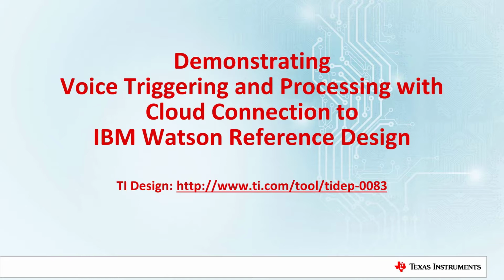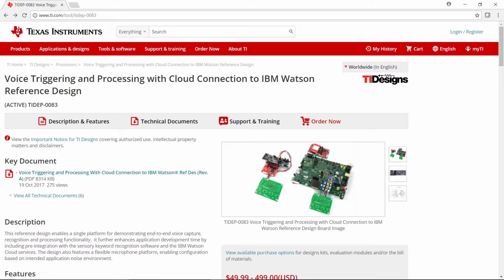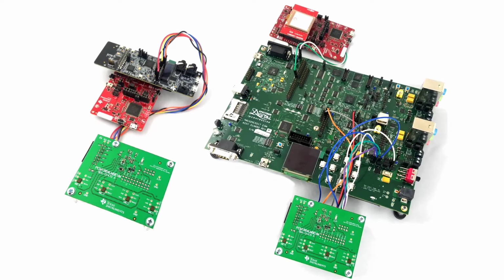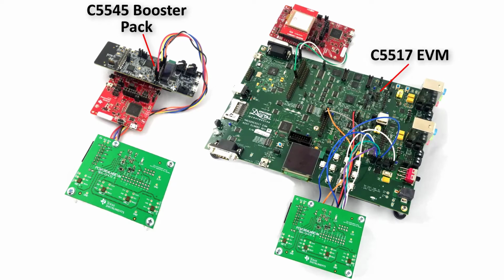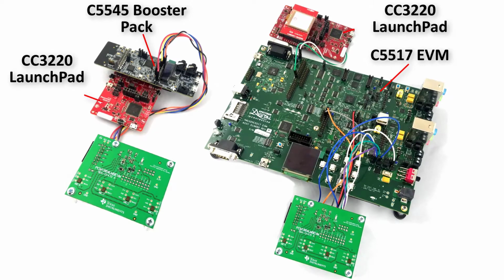Hi, in this video we will cover the demonstration of the voice triggering and processing with cloud connection to IBM Watson Reference Design. The demonstration of the TI design consists of two C5000 platforms, the C5545 Booster Pack and the C5517 EVM. They both essentially run the same demonstration, except that the C5545 uses 2 microphones and the C5517 uses 4 microphones. The CC3220 SF Launchpad is the backend for the Wi-Fi cloud connectivity.